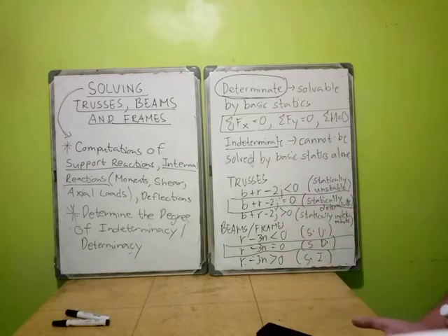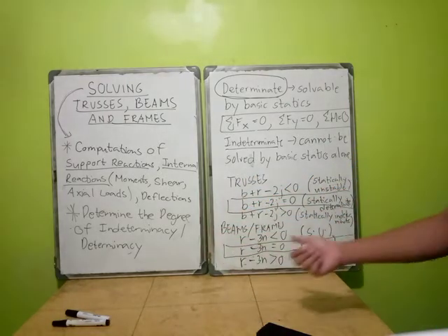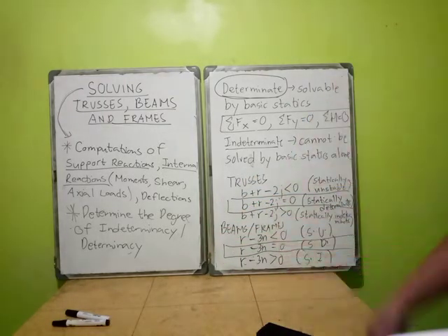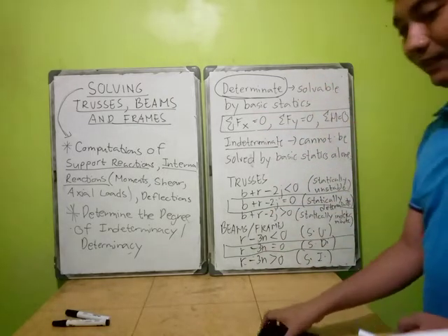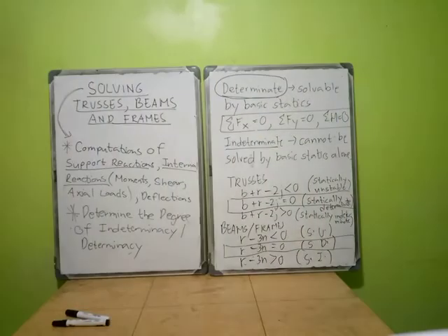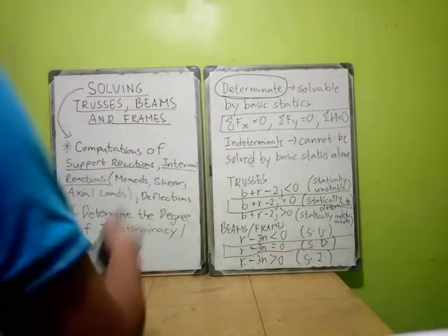First steps na dapat mong i-consider when solving truss, beams, and frames, which is the degree of indeterminacy or determinacy. Kapag determinate, then go na. I-solve mo using statics. So, okay, may I erase all of these things.